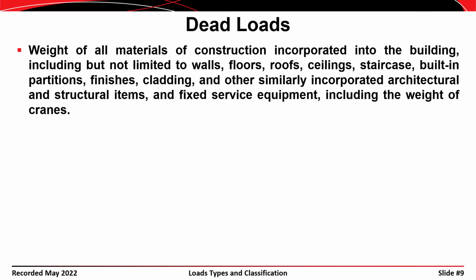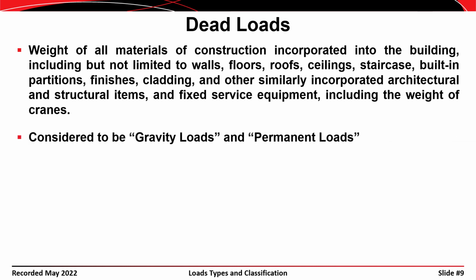There are built-in partitions like masonry walls and things like that, but there are also movable partitions like gypsum board on metal studs or gypsum board on wood studs, things of that nature. If it's a movable partition, it's part of the live load. If it's a built-in partition, it's part of the dead load. Okay, these are all considered to be gravity loads, and they're considered to be permanent.